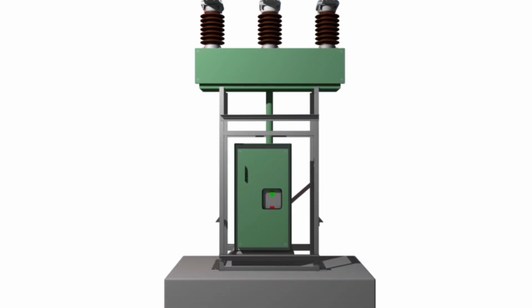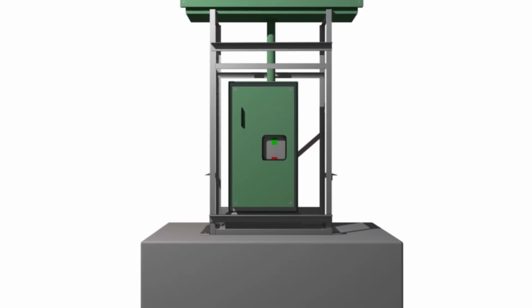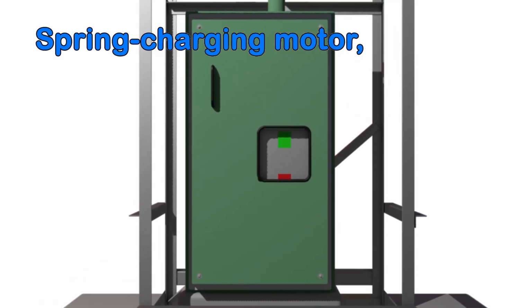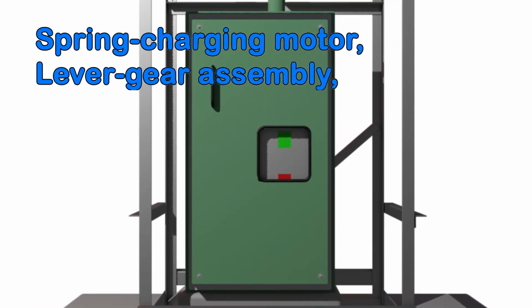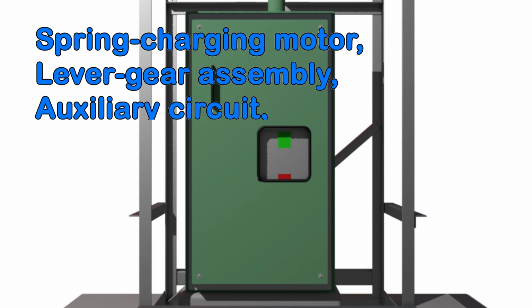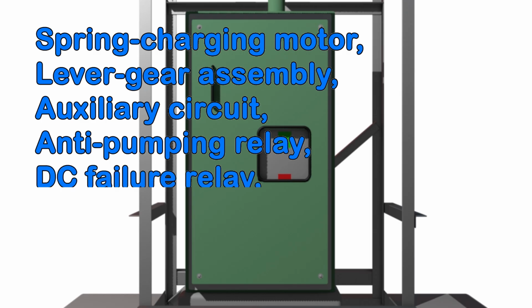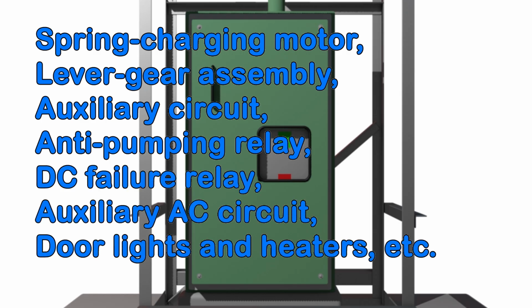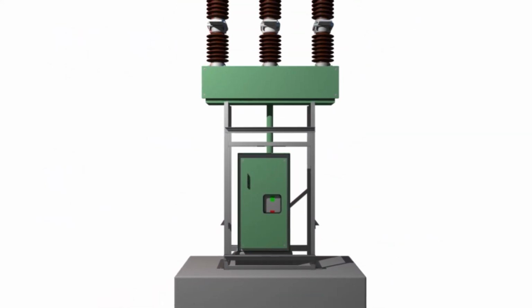This is the local mechanism. This is the mechanism box, which contains the spring charging motor and other lever gear assembly to operate the circuit breaker. It also contains the auxiliary circuit, as well as anti-pumping relay, DC failure relay, and auxiliary AC circuit for door lights and heaters, etc. This is the basic structure of the minimum oil circuit breaker.